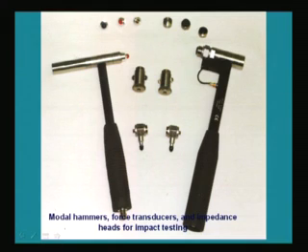This is another device called the impact hammer. Any dynamic system, if you want to excite it and see what the various natural frequencies of the system are, we use this hammer. As the name implies, it is not literally a hammer, but we just tap the dynamic system or the structure or the machine, and then, if you see here, there is a force transducer. So how much force we are imparting to the structure, it can give us in the time domain.